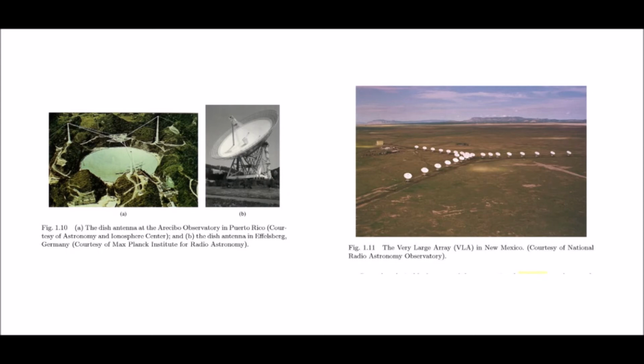Antennas which do not protrude from a surface are very desirable for fast-moving vehicles such as airplanes, missiles, and spacecraft. In the late 1970s, the military was especially interested in such antennas because they did not interfere with the aerodynamics of these vehicles. Historically, the microstrip patch antenna was developed in response to this need, although its planar profile has been found to be an attractive feature in commercial applications as well.